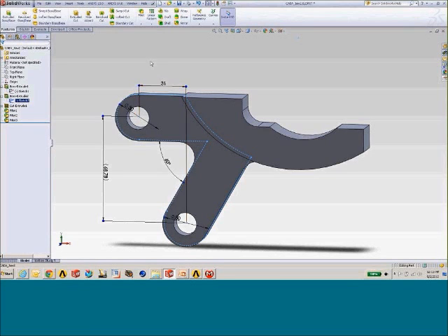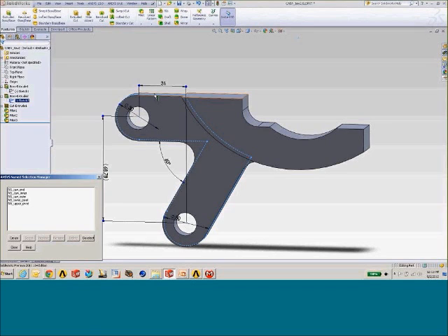Additionally, in your CAD tool, you have available to you the name selection toolbar from the pull-down menu. With the name selection toolbar at the CAD level, we can define geometric entities like surfaces or edges or bodies that we want to have a name assigned to when we bring this geometry into the workbench environment. Now, these name selections can also be defined downstream, either in Design Modeler or in the mechanical tool. But if you're comfortable with the CAD side and you like to do as much work as possible in the CAD tool, you can use the name selection manager at this level, and these name selections will propagate through the process.